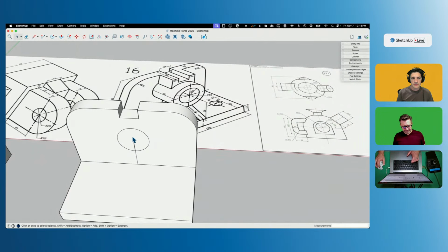Since SketchUp always draws circles by radii, I do have to do some quick math and divide 50 in half, which obviously everybody knows is 37. So 25. I know, I'm just kidding. I am trying to always go on an axis with circles. Just a good way to do it, a good thing to practice.